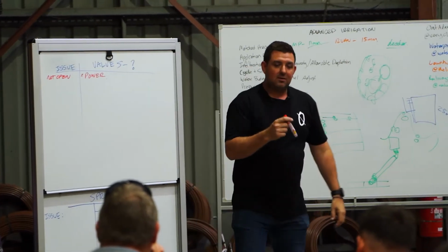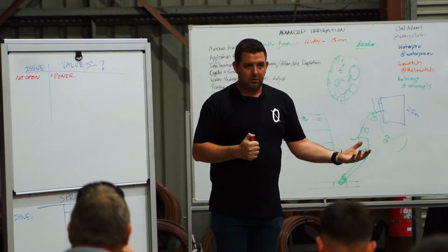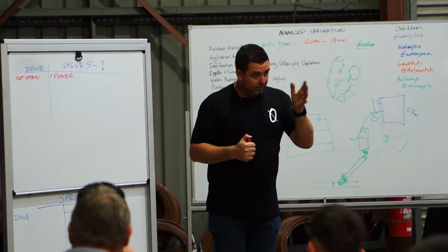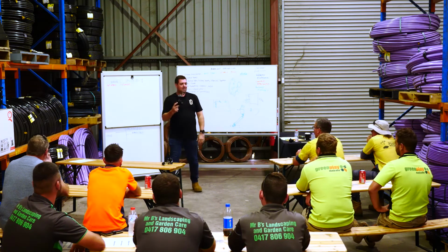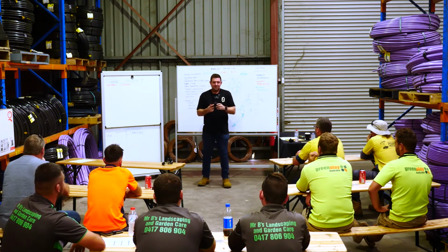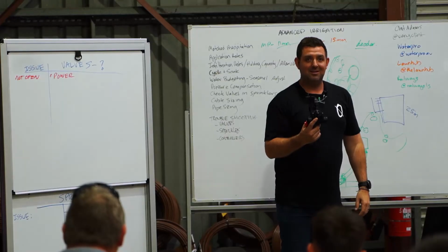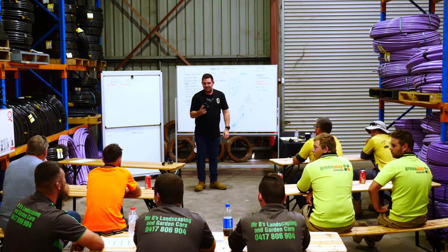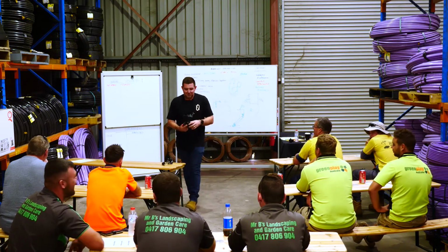It could be something as simple as the ball valve's not on, right? So if the ball valve's off, there's no water, it won't pop up. It could be the solenoid valve is facing the wrong way. You done that before? I have. So don't feel bad. Have you done it? Yeah. They've got arrows on them, but you're busy. You're busy, you've got a lot to do. You're trying to get the valves in.